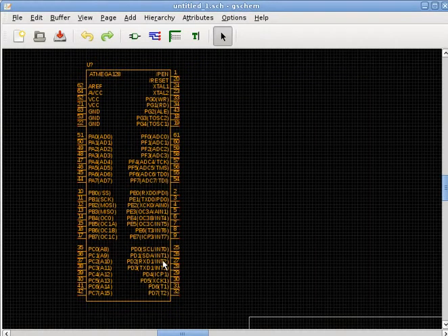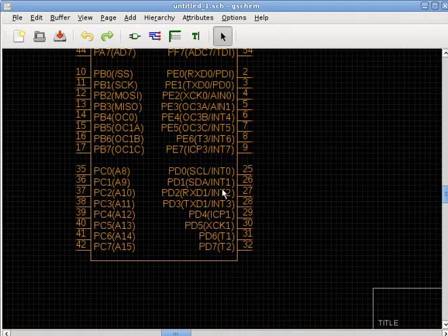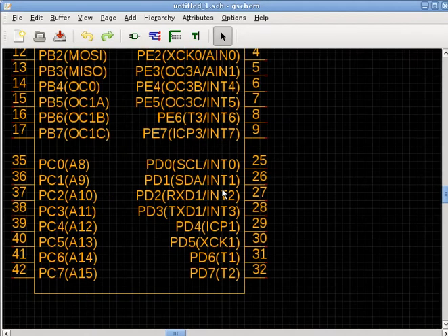In most of this software, like schematic capture software or PCB layout software, the user interface is not what you expect. In other words, they don't have the zoom control like most software. In this case, we use the lowercase z to zoom in and uppercase Z to zoom out, which is not very intuitive, but that's the way they usually write this software.